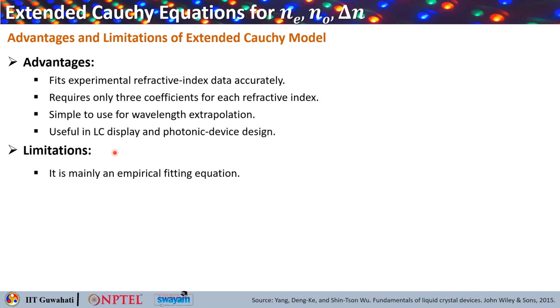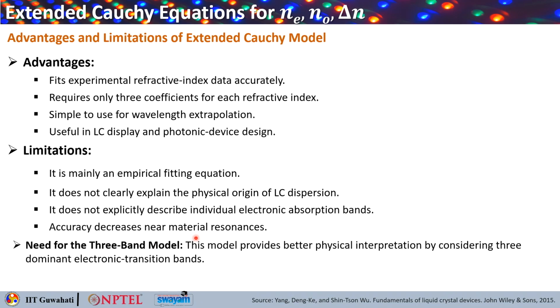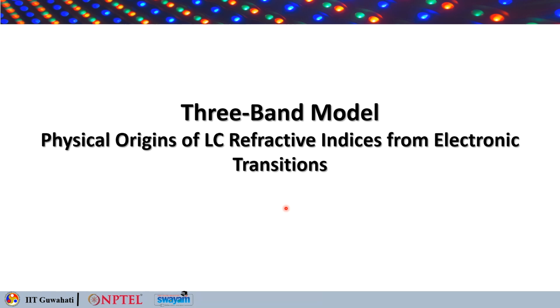Now, all is not good, there are some limitations. The thing is, it is mainly an empirical fitting equation, right. So, it does not clearly explain the physical origin of the liquid crystal dispersion, and it also does not explicitly describe individual electronic absorption bands. So, you will see that the accuracy basically decreases near material resonances. So that brings you to the requirement of the 3-band model, which will be able to provide better physical interpretation by considering 3 dominant electronic transition bands. So now let us look into that.